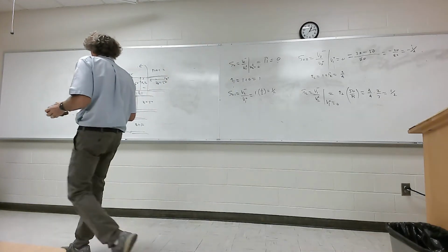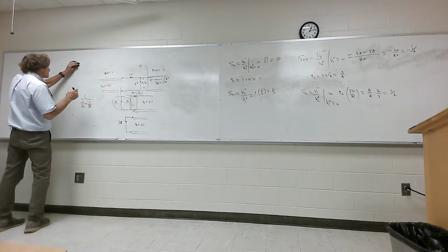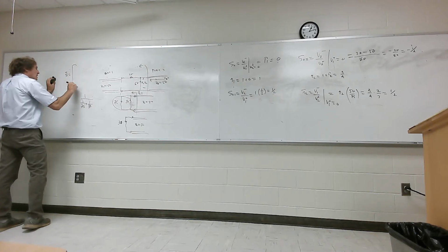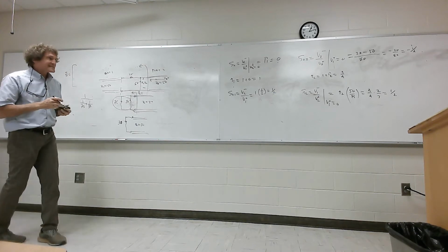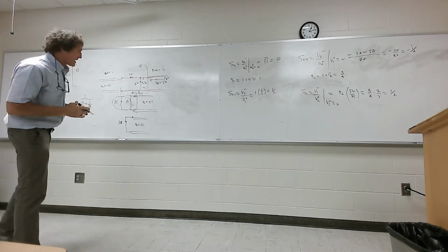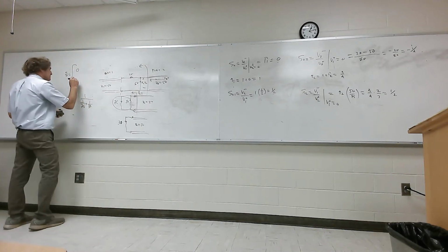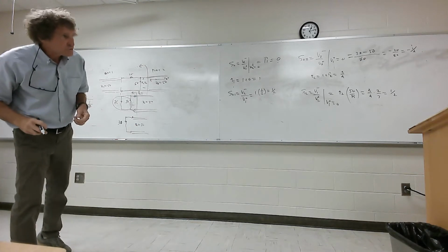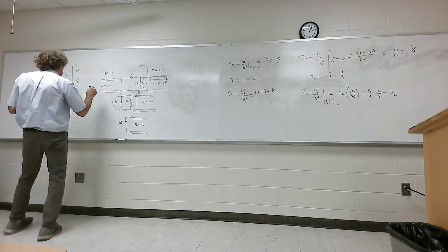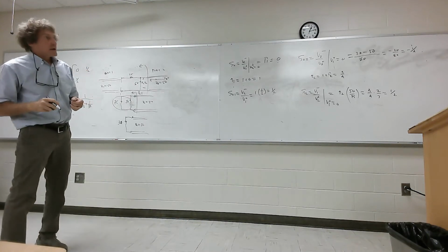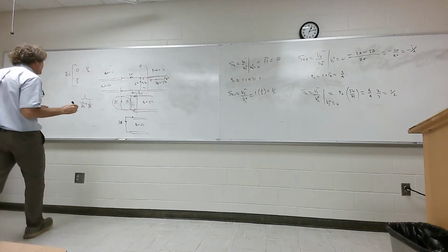All right, so now we can say that when I get the S parameters for this network, and this is in the book, I have S11 is 0, S21 is 1/2, S12 is 1/2, and S22 is -1/4.